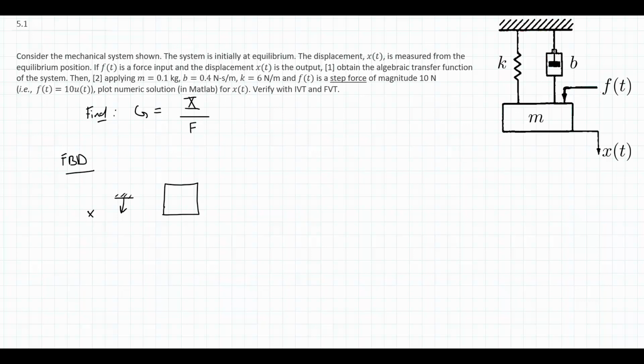It's just that our inference at the end would be the opposite of what's positive and what's negative. All right, so on this mass m, we are going to have forces from the spring and the damper to which it is attached. And we saw this before in section 3. For springs and dampers, I'm always going to draw them in tension. And I'm going to derive their values assuming tension. So positive tension, negative compression.